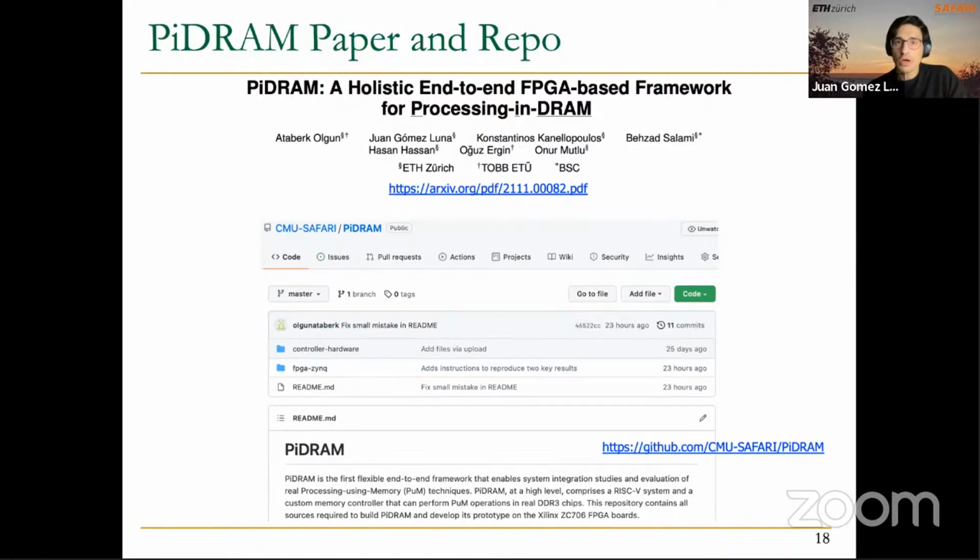So we have a couple of works, probably more, that propose different ways of doing computation using DRAM. The first paper was RowClone that explained how to copy one row to another row inside the same subarray. The second one was Ambit, a way of executing bitwise operations, logic operations inside DRAM by activating 3 rows inside the same subarray at the same time.